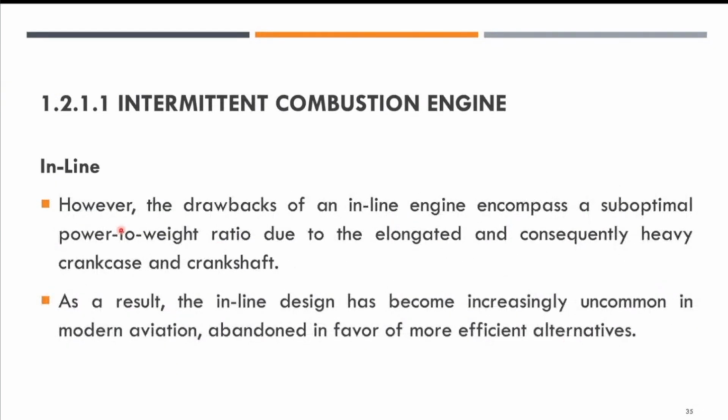All right, there are drawbacks. The disadvantages of an inline type of engine include a suboptimal power to weight ratio, because of the elongated and consequently heavy crankshaft and crankcase.